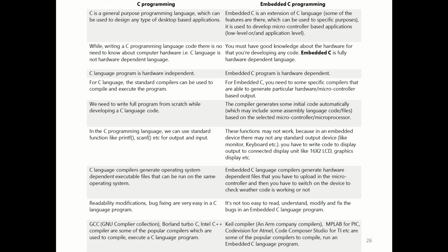So finally, embedded C is a choice. Hardware target device is a choice. Peripherals is a choice. So the compiler is altogether different for different companies, different architectures. Though the syntax is the same C syntax, you don't need to learn a new syntax. The way you define the variables, the way you define the functions, the way you define the structure, the way you use the conditional statements, everything is the same.